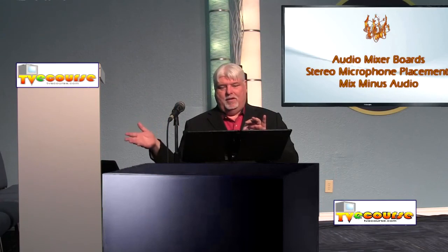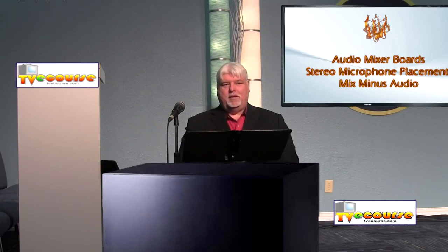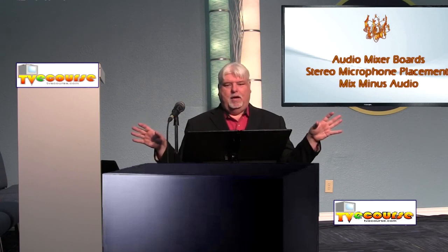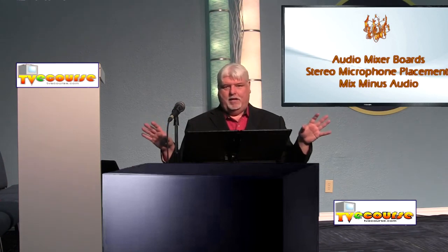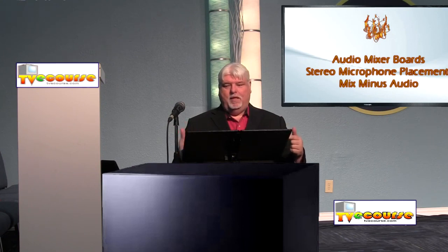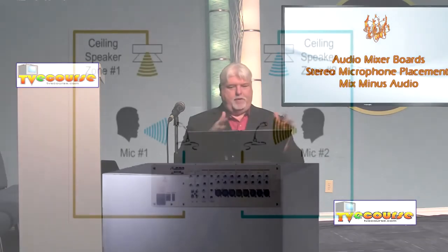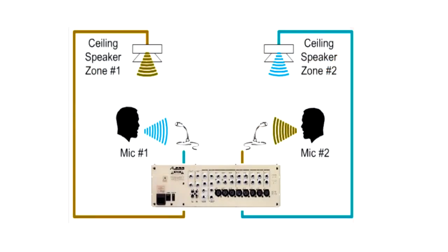And what would a purpose be for a submix? Well, there's a term we use called mix minus. Let's say you have a bunch of people, or you're listening on a telephone, or you have someone talking in a reinforcement situation where the audio is being reinforced in the room. You want to avoid feedback, and so let's say you have someone that has a speaker right in front of them. They're speaking at an event, and they have a speaker, and that speaker is feeding them not program, but audio from the mixer.